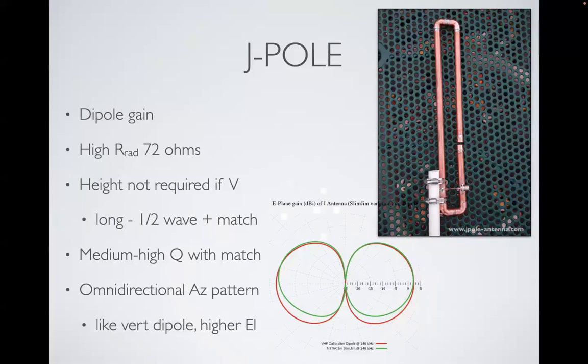And in this case, we have a transmission line transformer at the bottom. And well, you can see the short part, right? So that defines a boundary condition. So it's 0 ohms down there. And then we move up a little bit for the given wavelength, and we find that we can find sort of the 50 ohm point-ish. It might be slightly reactive, but that's okay. And then the impedance continues to transform as we go up that transmission line transformer until we get to what looks like kind of an open circuit-ish thing, which is what we want to feed a half-wave dipole.